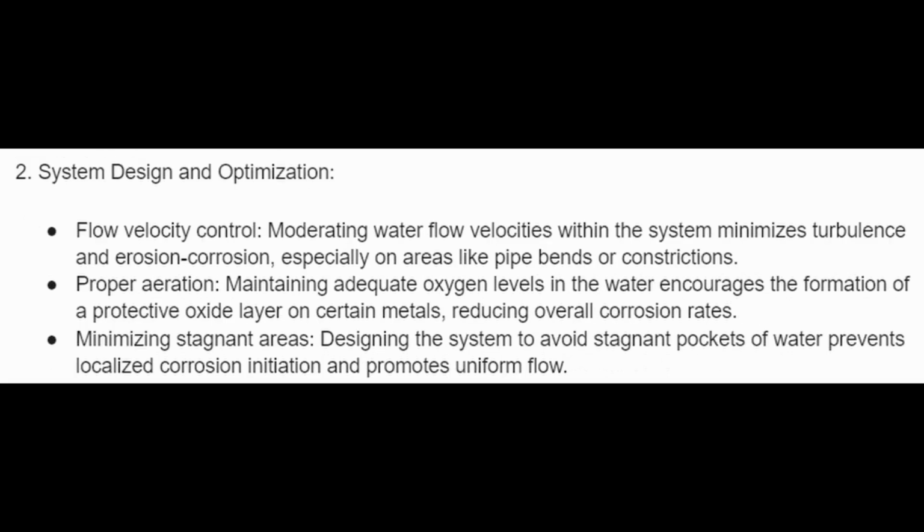2. System design and optimization. Flow velocity control: moderating water flow velocities within the system minimizes turbulence and erosion corrosion, especially on areas like pipe bends or constrictions.